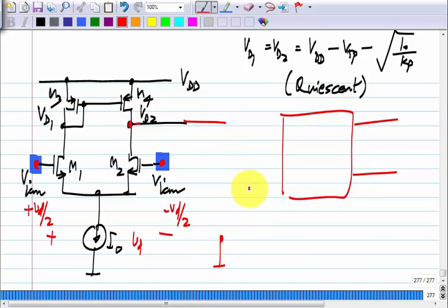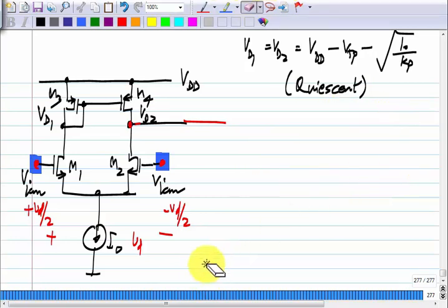All this Thevenin Norton work only for linear circuits. So, when I say Thevenin equivalent, I mean the Thevenin equivalent of the small signal circuit corresponding to the differential pair. That is what I want to do, and it turns out that the Norton equivalent is easy to find.